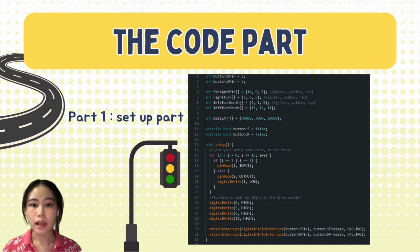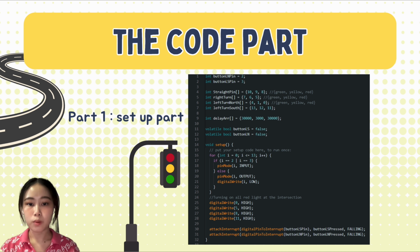Next, in lines 11 and 12, we set the buttons for left side, north and south, to false. In the setup method, we set pins 2 and 3 as input because 2 and 3 are the buttons. Other pins are output and set to low. Then we set high at pins 5, 8, and 11, which are the pins for red lights.